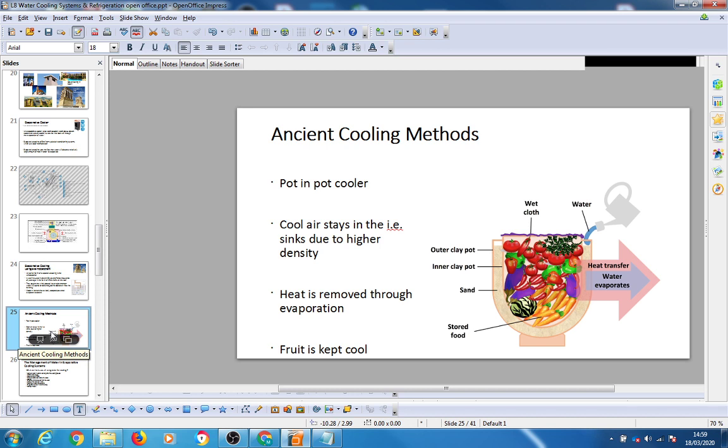There's this band of temperatures, and we need to keep it either above or below to stop Legionnaire's disease from developing. By the way, you can drink it and it doesn't do you any harm, but if you breathe in droplets, similar to this corona stuff that's going on now, that's a killer. That's what can give you Legionnaire's disease. It's a bit like flu symptoms. Jimmy, rust, big problem as well. Thank you for that. Rusting is a problem with water as well, especially when you've got an evaporative system made of steel and metal.